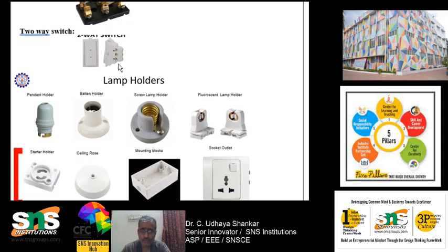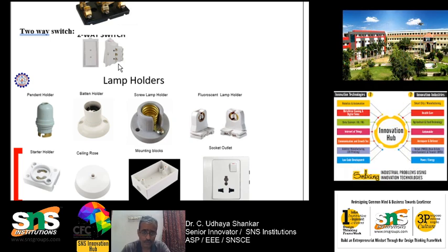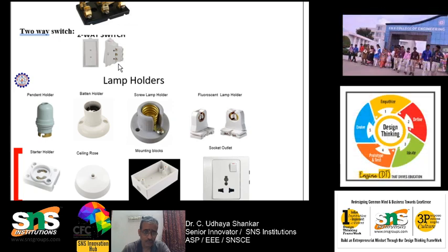The next is the two-way switch. As we have discussed earlier, it will be used in our bedrooms or even staircases, everything. Because at the entrance we need one switch, and near the load we need one switch. So this is the advantage of the two-way switch: we can operate two different switches independently.